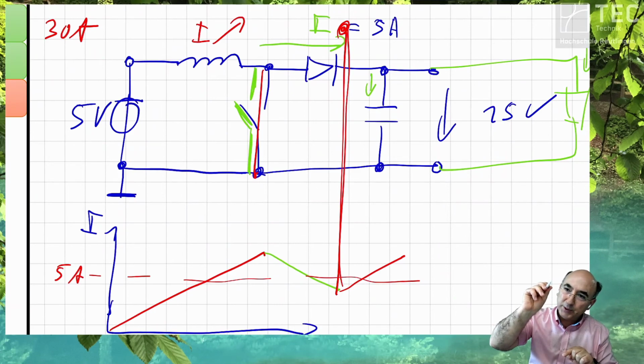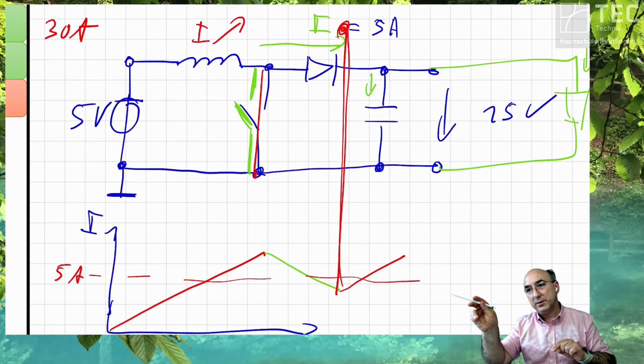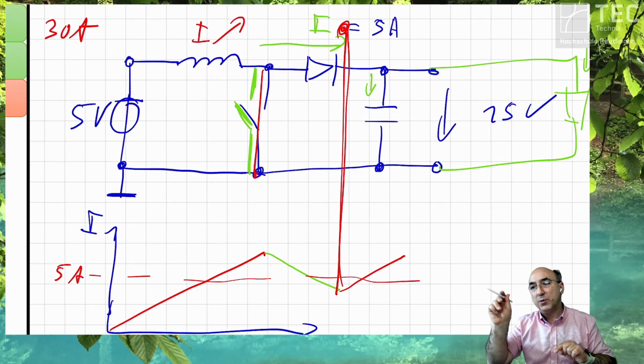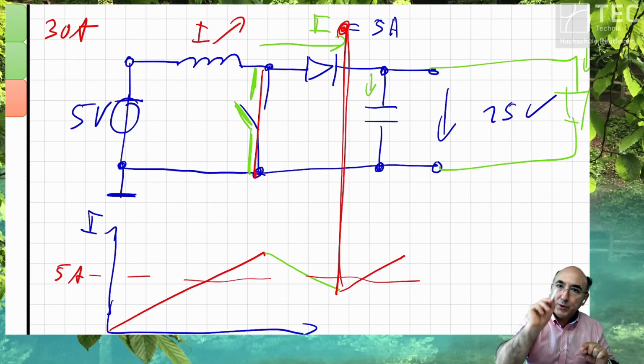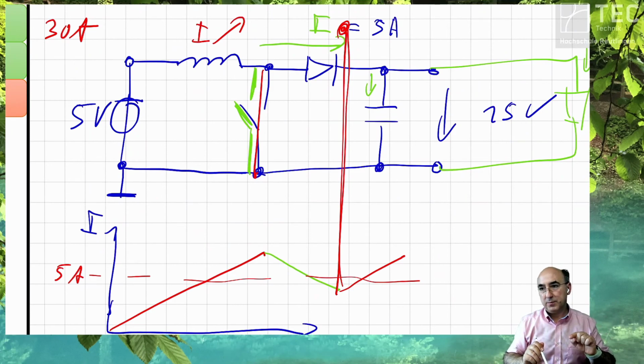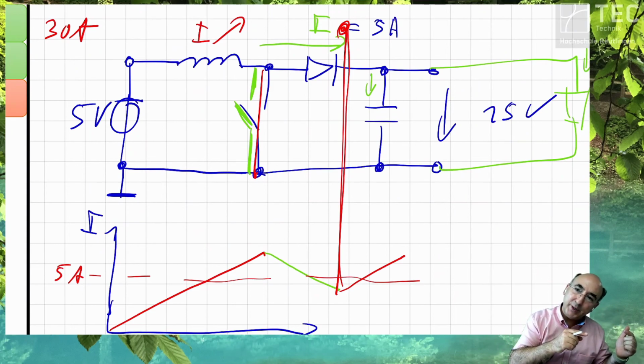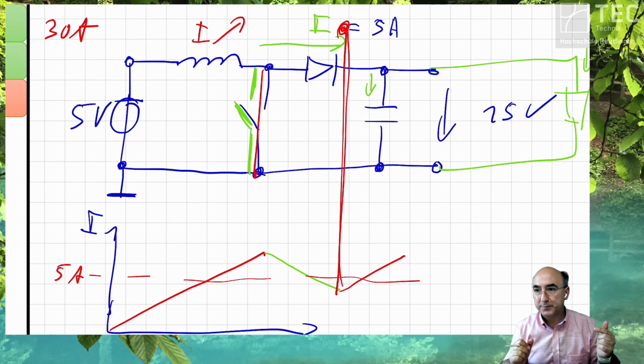Having a high Schottky barrier, your reverse current is not so high. But you have a forward current without stored charge, without a diffusion charge. Therefore, in applications where you need very high efficiency, you can afford to take the silicon carbide diodes, which are a little bit more expensive.